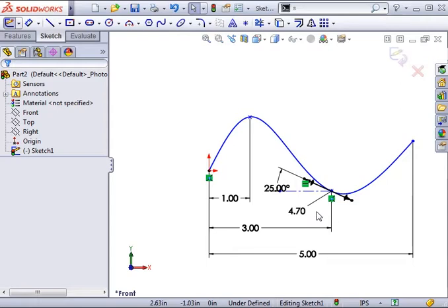That being said, I generally tend to only create 3 or 4 point splines for serious projects. That way I can fully define and dimension the spline geometry in order to create accurate drawings for manufacturing. However, if you're modeling something for fun and just want to get something close to the general shape of the design, then the spline can be a quick tool to use to create a complex sketch shape, as long as you don't care about fully defining the sketch.